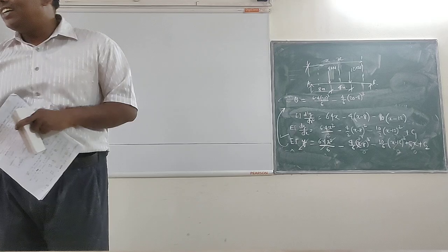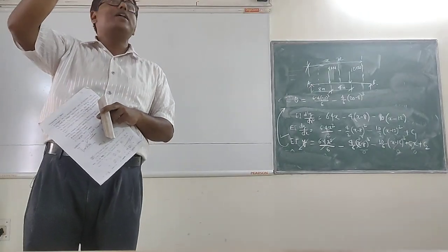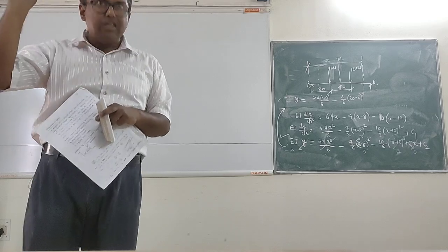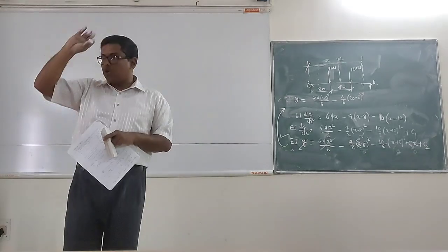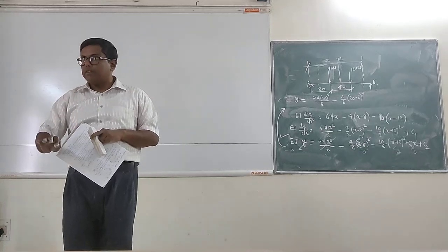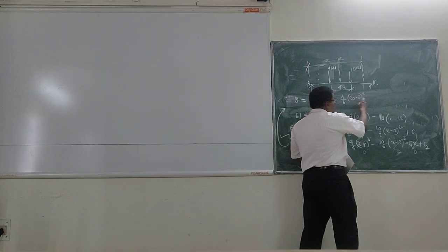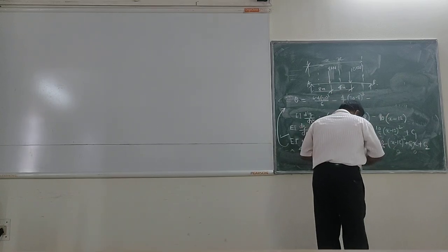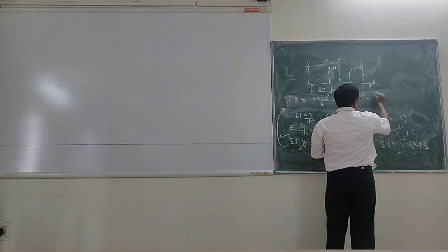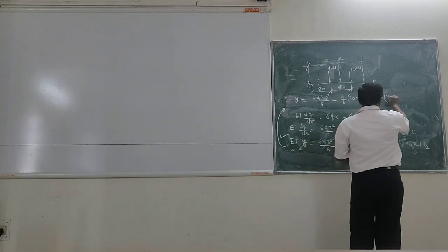You cannot consider it as in the previous place. What happened there? We did not take the cube of minus 8. We have taken minus 8 as equivalent to 0, as per Macaulay's condition. Now here I have to evaluate because this term is positive. Now the next term is 10 by 6, (20 minus 12). Positive or negative? Positive.